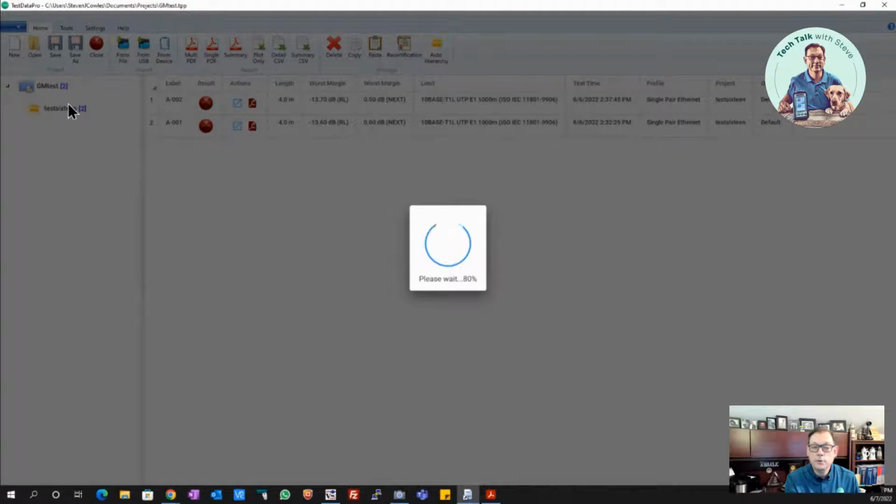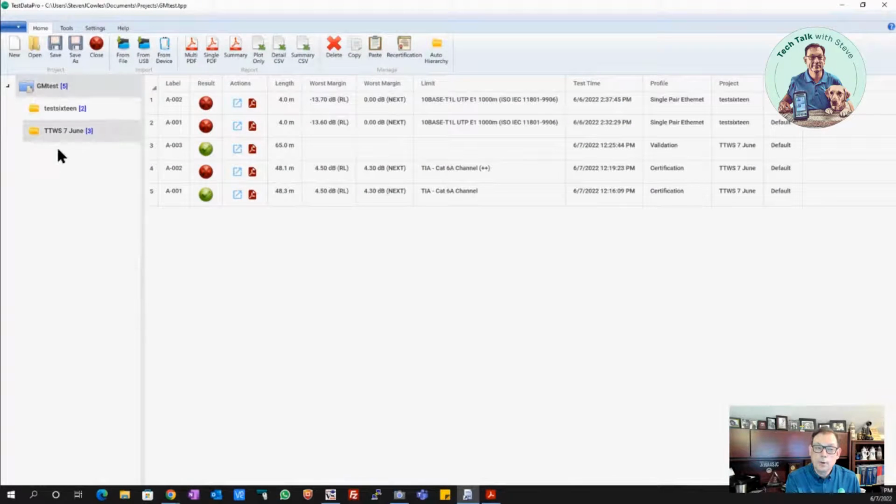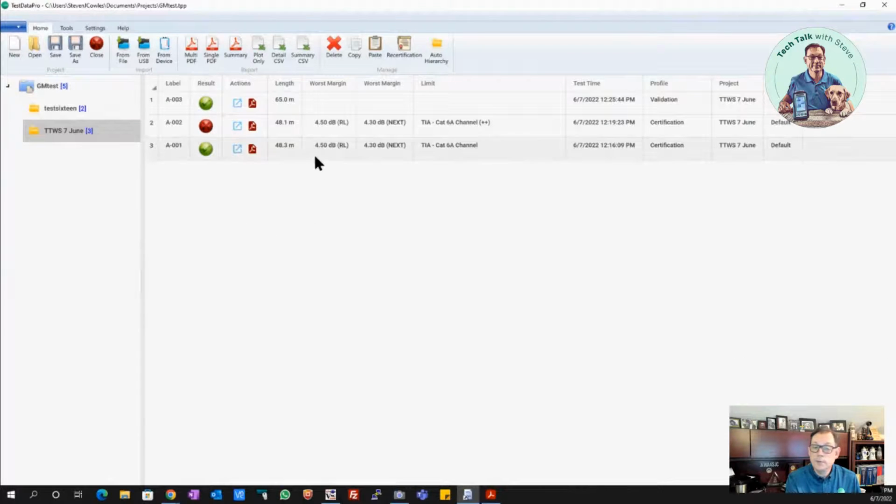And once my test results come in, I'll pull them up. So here we've got our tests from today. And we can see we've got that one failed certification test right here for the DC resistance unbalance. We've got the test for the multi-gig and PoE, and we've got our past tests.